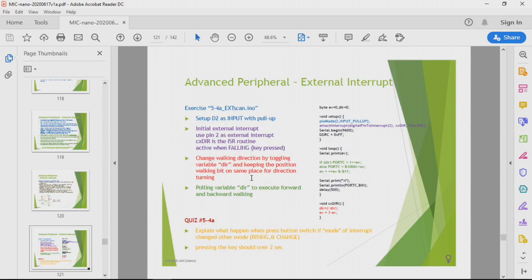So for this example, we set up pinMode for D2, interrupt 0, as an input with pull up. It looks better and easier than the traditional register setup, just a simple sentence with some conditions. So you can consider using that, but you should know how to use the traditional method to set up those environments.